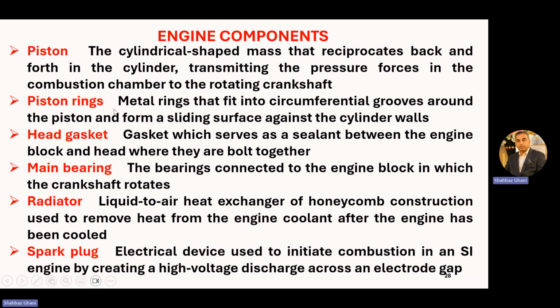Piston ring. Metal rings that fit into the circumferential grooves around the piston and form a sliding surface against the walls. These are basically of softer materials as compared to the pistons. These are the rings that fit into the circumferential grooves around the piston and form a sliding surface against the cylinder wall. There are two types of rings, compression rings and oil rings, or call it scraper rings.